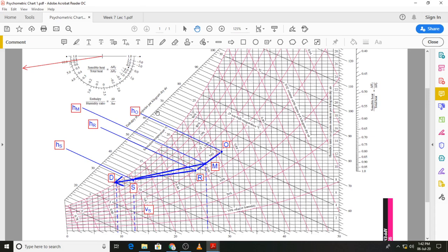The supply air is at 12.5 degrees C. So you can see I have got this line over here which is at 12.5 degrees C, but I need some other information using which I will have to locate state S, and that is the sensible heat factor. So what I did is first I went to the protractor and I drew a sensible heat factor line which corresponds to the conditioned space, that is the space condition line, which has a value of 0.783.